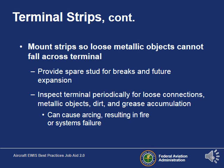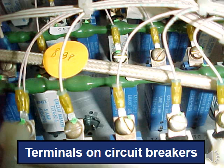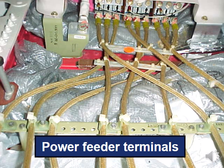It's important that metallic objects and other debris cannot fall on top of the terminal strips. So if you do have to mount a strip somewhere on the aircraft, make sure that it's in a place where gravity is not working against you. In some cases, where terminals attach to a certain point, there needs to be a torque. So in this case, you'll notice that there's torque seal to show the mechanic right away if there has been any rotation with the terminal.